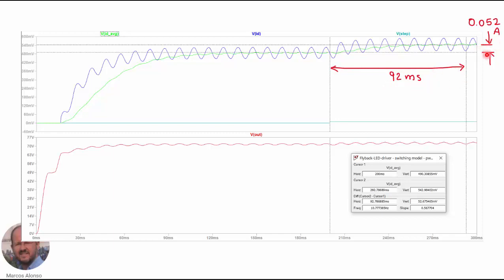Also, the amplitude resulting from the step should be 1% of the value corresponding to the unit step response, and this should be something like 49 milliamperes, while we are getting here 52 milliamperes, so it's also quite similar. So with this we can say that we have verified our dynamic model by using a step-up transient simulation in LTSpice.